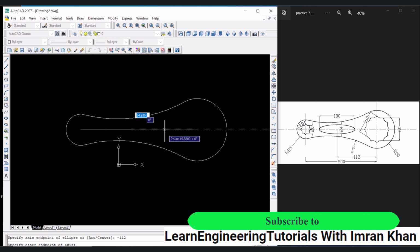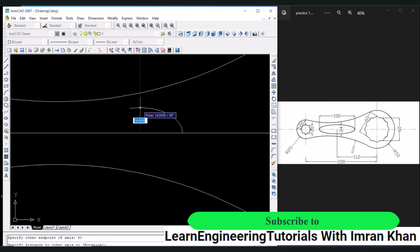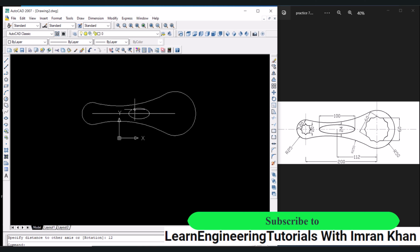Now the other end point of the axis, so for that we will just give it the value of 50, enter. Similarly, in the y-axis direction we will give the value of 12, enter. So now we can see that this ellipse has been formed incorrectly. Click on this ellipse and let's find out the dimensions. So here we can see that one dimension is 25, which is wrong, it should be 50, and the other dimension is OK, which is 12.